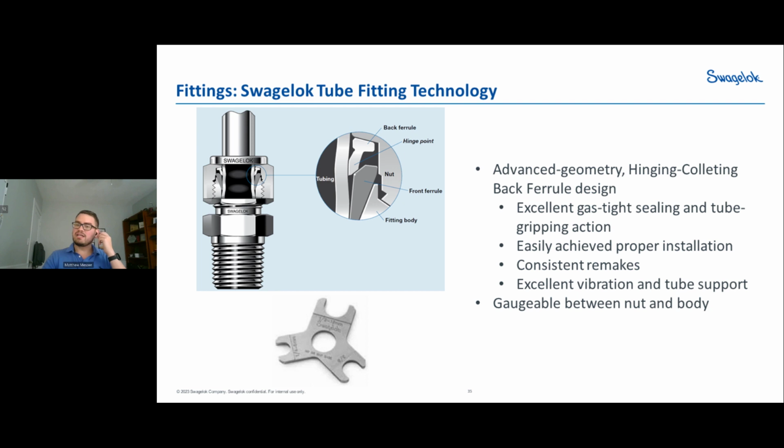With our back ferrule design, it does create a really great gas tight seal. It also enables us to get pretty consistent remakes as you go through its life cycle. And as I mentioned prior, there is a gaugeable surface between the nut and body. That really makes it easier for the end user, so you can make sure that your fitting is pulled up properly.